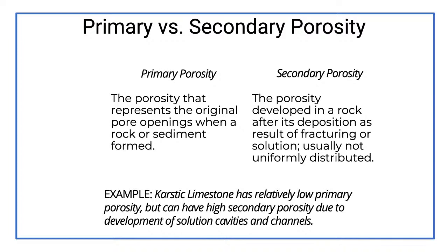A lot of times in alluvial aquifers, you can move the well 100 feet this direction or that direction and get pretty much the same results. That is not true if you're in a fractured bedrock. It comes down to exactly hitting those fractures. And that's a lot of what I do, tracking down those fractures and getting the best well possible in the circumstances. So here's an example.